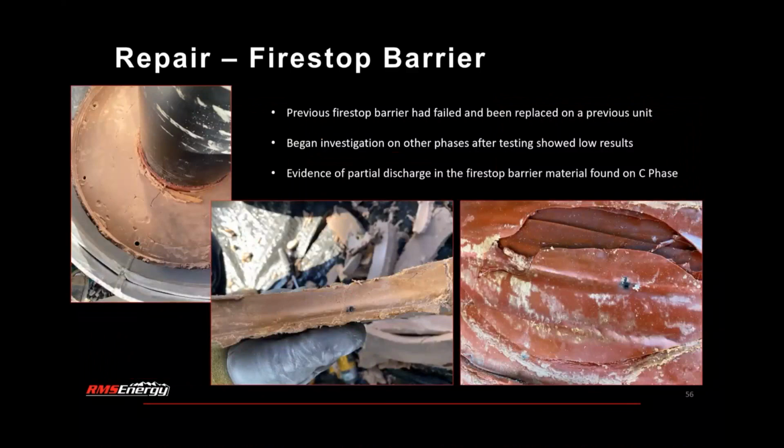Ultimately, it led to complete replacement of the entire starter cabinet. So as part of the repair and the investigation, it was found that the previous fire stops had failed. This was a known issue on this plant with this design of fire stop. So we began investigation on the other phases and other units.